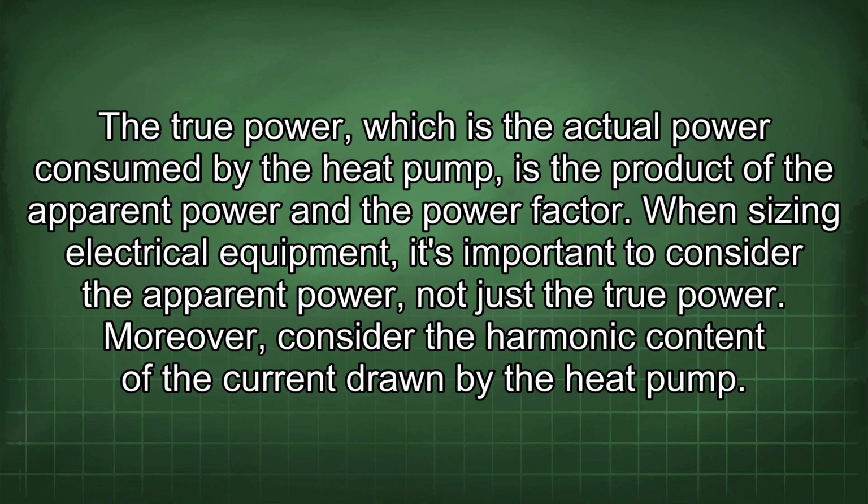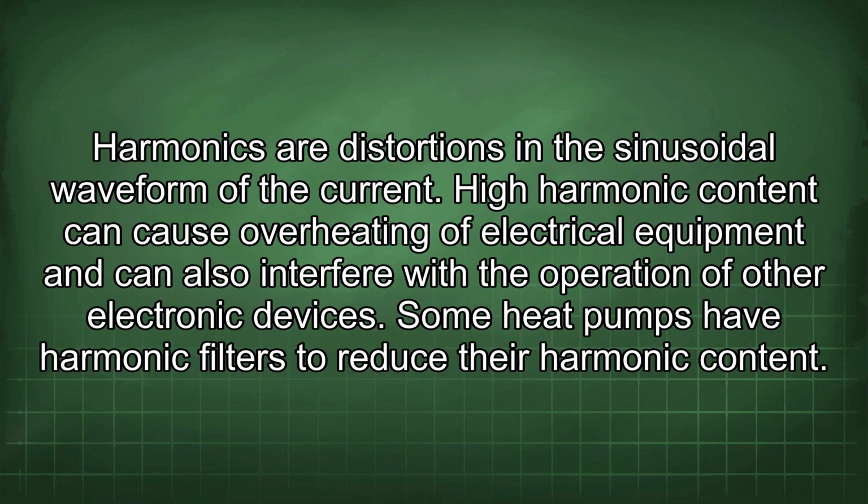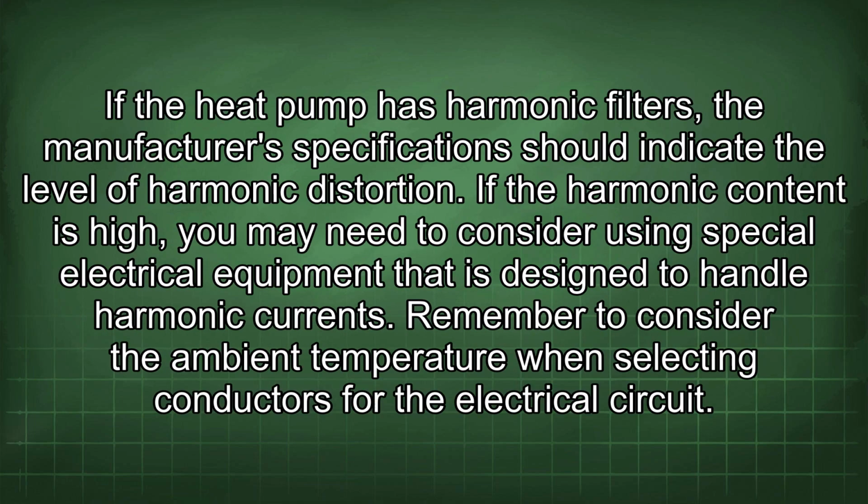Moreover, consider the harmonic content of the current drawn by the heat pump. Harmonics are distortions in the sinusoidal waveform of the current. High harmonic content can cause overheating of electrical equipment and can also interfere with the operation of other electronic devices. Some heat pumps have harmonic filters to reduce their harmonic content. If the heat pump has harmonic filters, the manufacturer's specifications should indicate the level of harmonic distortion.